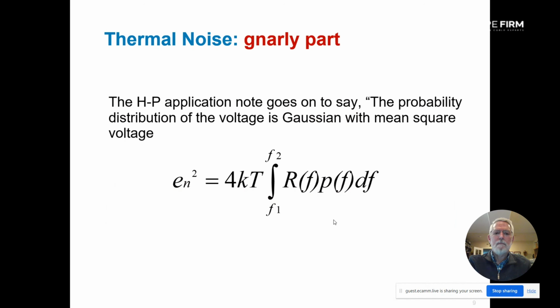But check the instructions for the spectrum analyzer to see how you need to configure the analyzer to do a marker noise measurement. That, in my opinion, will probably give you the most accurate measurement of a noise-like signal and the noise. Great. Thanks for the question, Peter. Yeah, that's a good question.